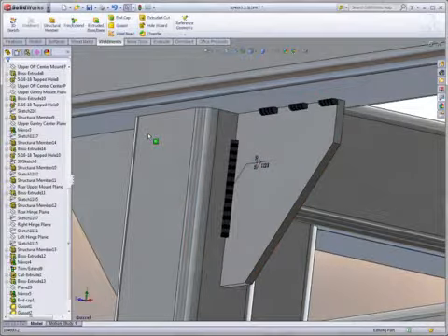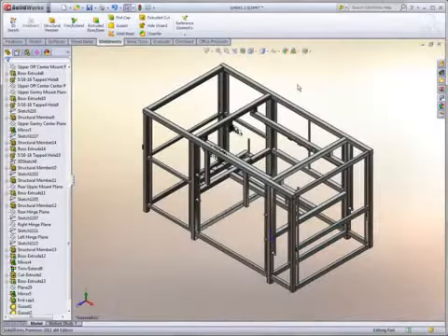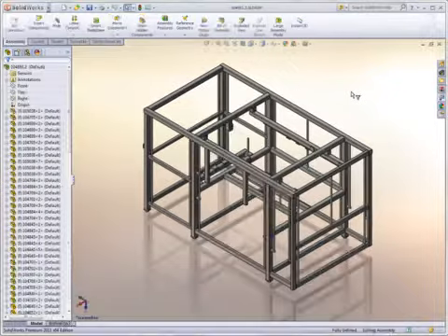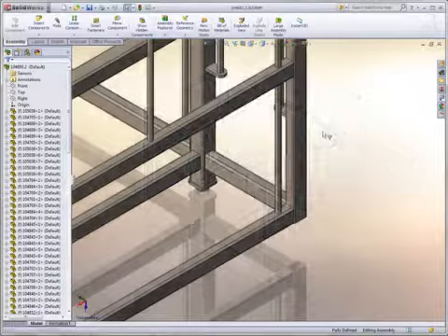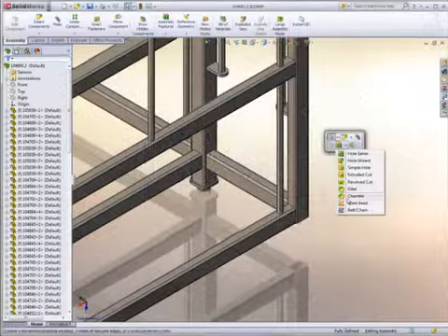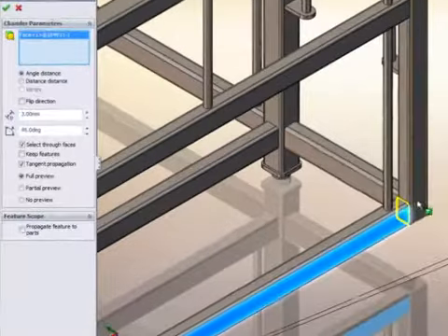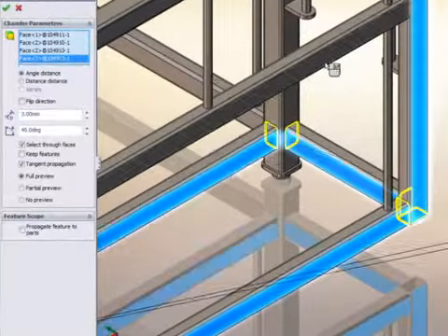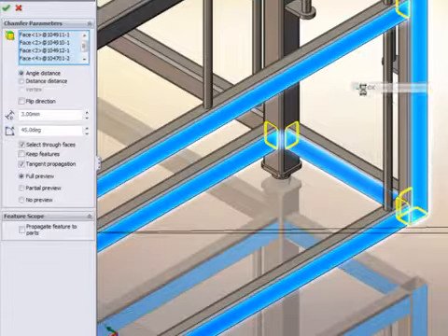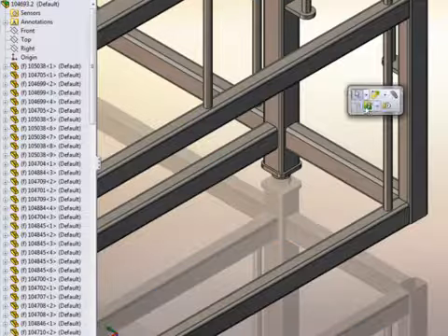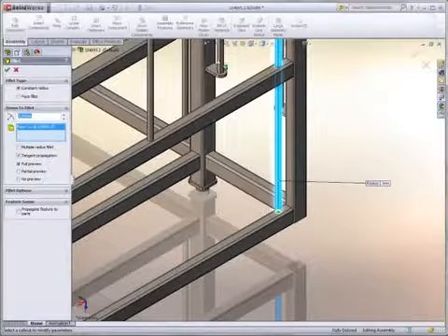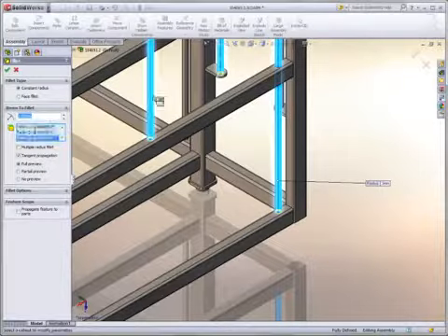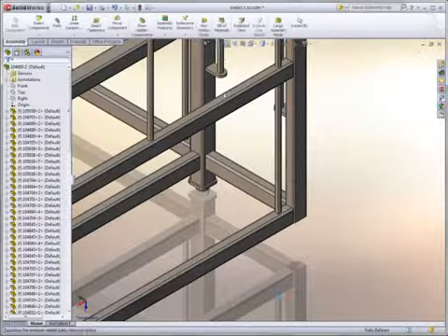In the past, creating weldments was primarily done in the part modeling environment. SolidWorks 2011 brings these capabilities to the assembly environment as well, letting you create weldments at the assembly level. To make this work, assemblies need to support weld preparations. SolidWorks 2011 supports new assembly-level features to accommodate this. Specifically, chamfers and fillets can now be created at the assembly level to allow for these cases.